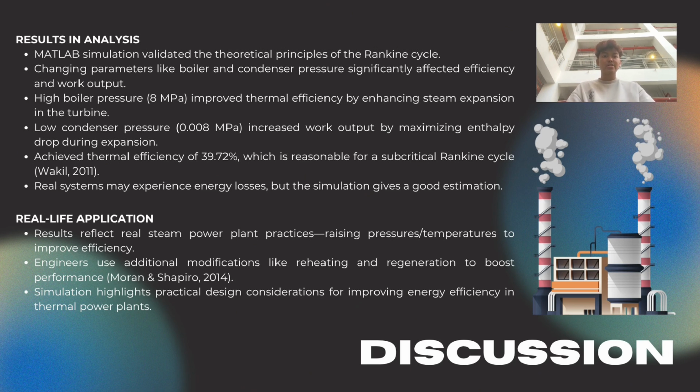On the other hand, using a low condenser pressure of 0.008 MPa increased the work output by maximizing the enthalpy drop during expansion. As a result, the simulation achieved a thermal efficiency of 39.72%, which is reasonable for the basic Rankine cycle under these conditions. While the actual system may include energy losses that reduce performance, this simulation still provides a realistic and reliable estimation.